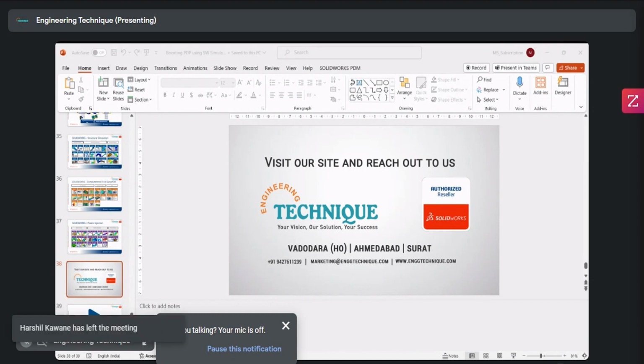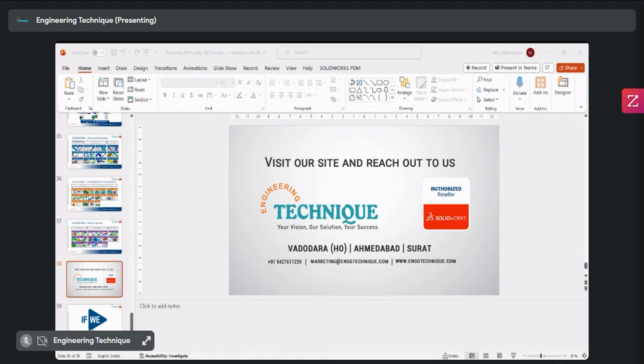As you saw, you removed the fillet and all from the design to the normal design. So do I need to do this with my finished design before the simulation starts? See, it is the ideal procedure that will help you to reduce the mesh size. Otherwise, in that fillet, a smaller mesh size is created, and that will lead to an increase in computational time.